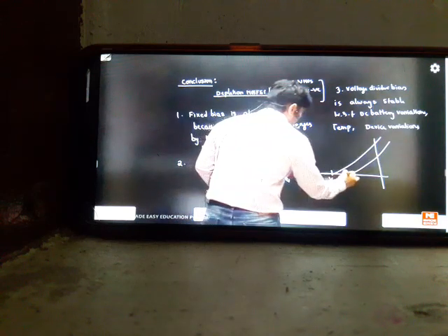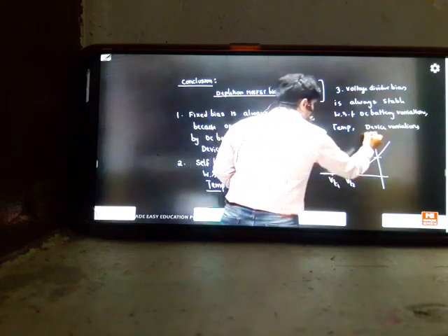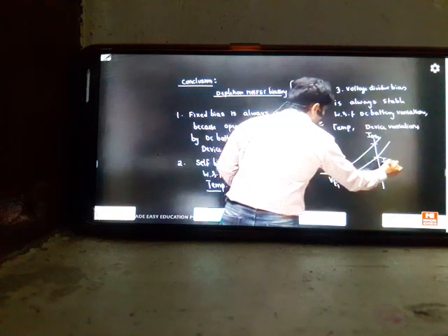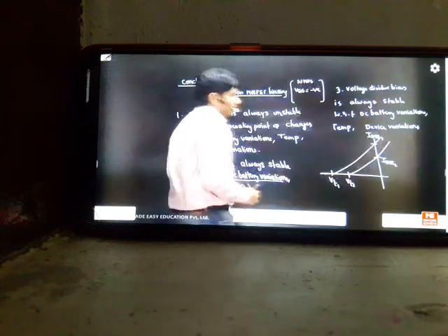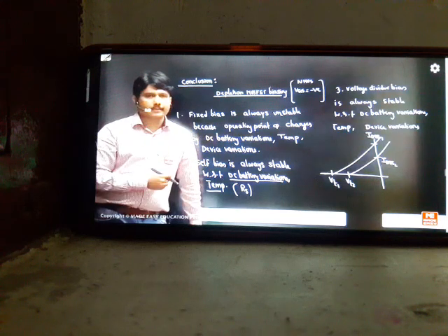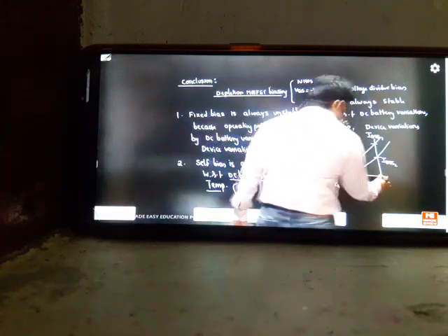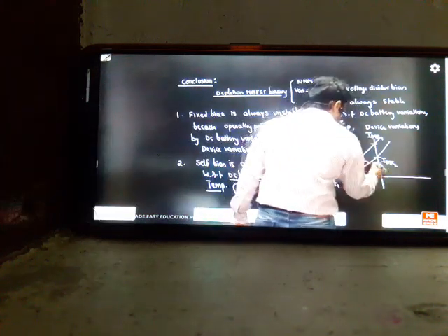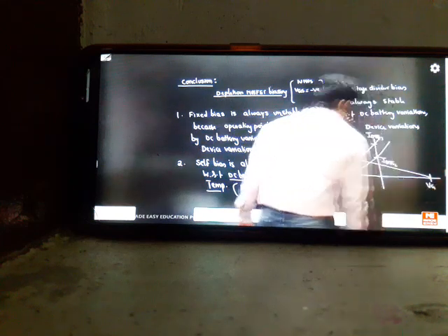This is VT1. The threshold voltage has changed to VT2. This current is IDSS1. This current is IDSS2. So like this your device can vary. If you replace one device with another device, the threshold voltage can change slightly and your actual values change. Now, whatever load line we applied, suppose this is your load line.